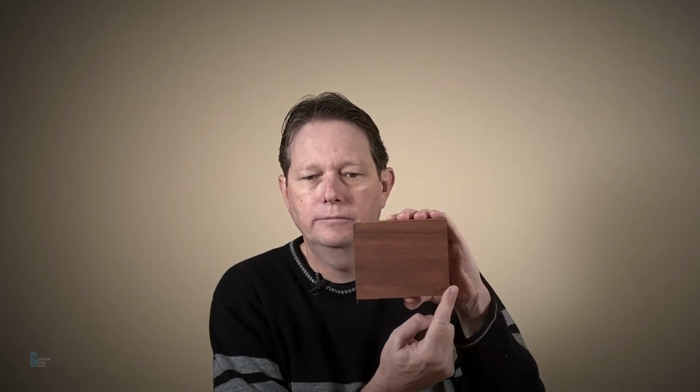Now, consider this block of wood is the physical representation of that sketch. The origin point is still down here. Move that around. Again, you can see that the origin point moves, but everything else is relative to it. And this is how planes work in FreeCAD's Part Design workbench.